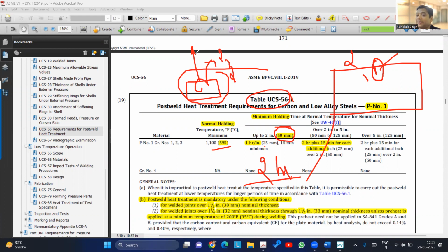So if I have already done three cycles, then I'm not worried, even if I've done twice, I know that I have the properties after three, so I can justify that my heat treatment has not affected my material properties and my design is valid. So that is the reason the test coupon will see three or four PWHT cycles.